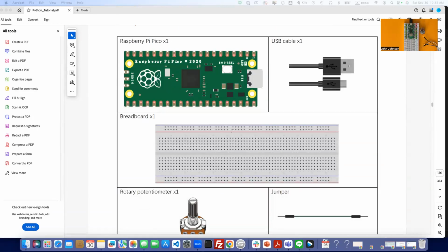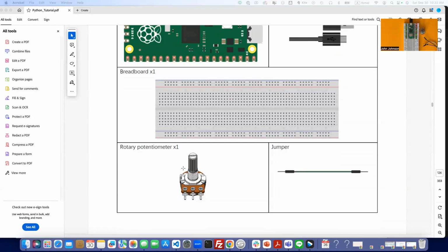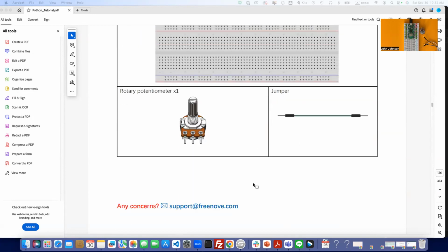We've got our usual suspects up here, but we're also going to have the potentiometer, the rotary one. We have 3 of these, I believe, in our kit. You'll probably notice that the legs are a little bit messed up on some. You can straighten those out pretty well, but you're going to be plugging that down onto the board with the actual turn stick facing you. And you're going to need 3 jumpers, maybe a medium to long size one, a medium, and a small.